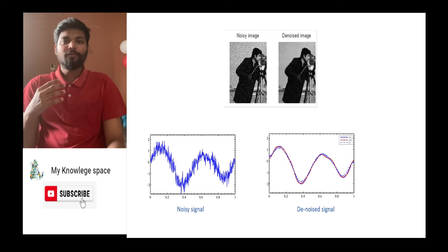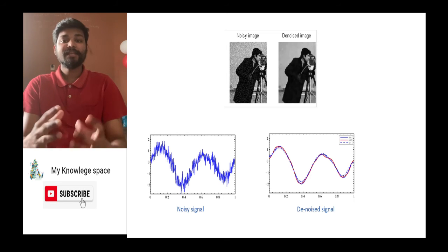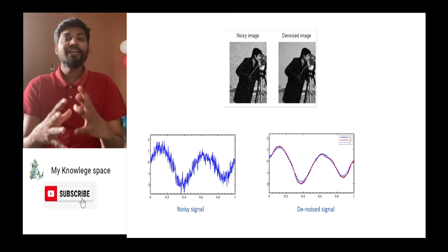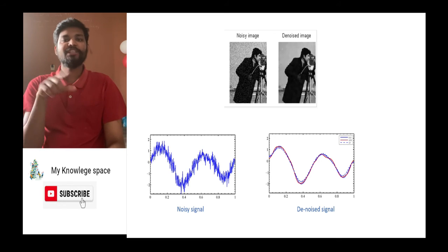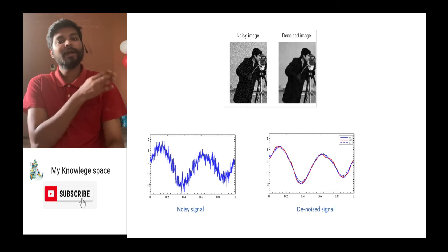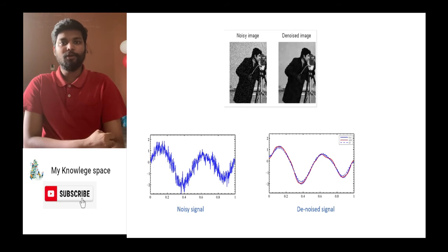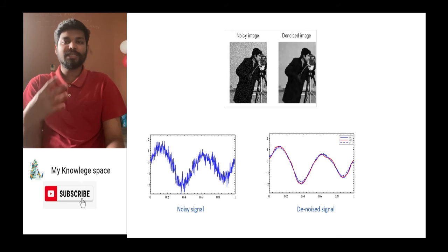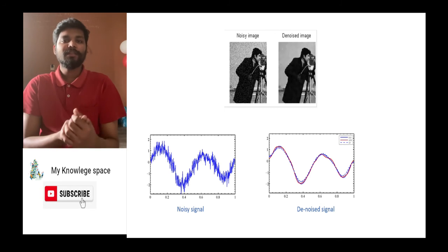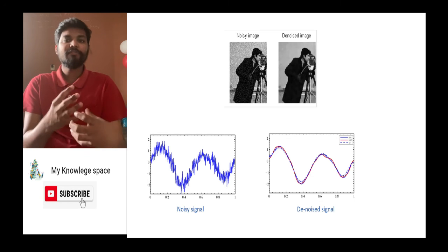Another advantage of this DWT is it has an ability to represent the natural components well. That is, it is able to represent the natural signals better compared to the CWT transform. Another big advantage is it does not have any redundant variables, thereby reducing the amount of issues caused in the analysis, and also it takes up less memory, thereby giving us a better result far quicker.